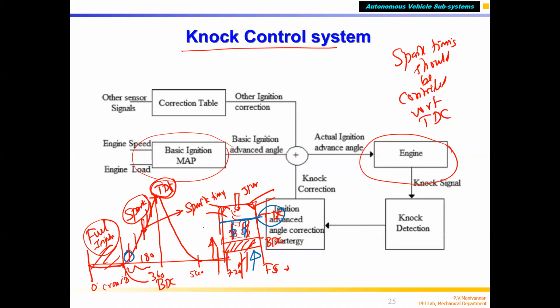The pressure will be higher if the piston has moved close to this condition, almost close to TDC. At that time the air fuel mixture is already compressed. We say the compression ratio is 8:1, correct? This is called the compression ratio in a petrol engine. In a diesel engine, you can go up to 15:1. If the compression ratio is higher and you burn the fuel in the compressed air fuel mixture, then all the fuel burns and you get the highest pressure.